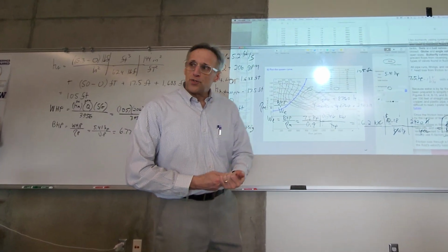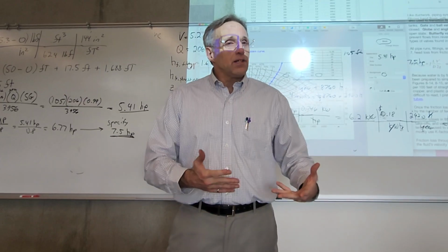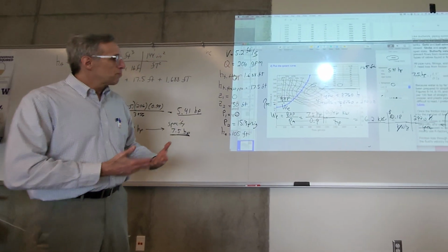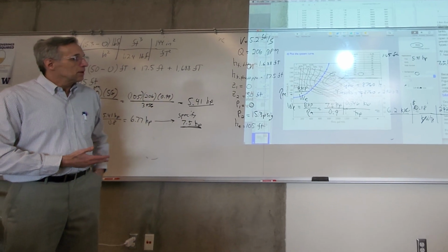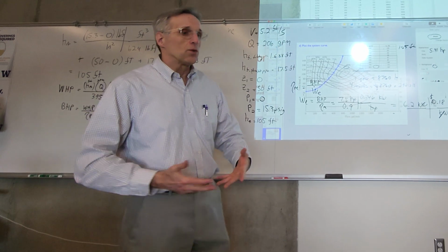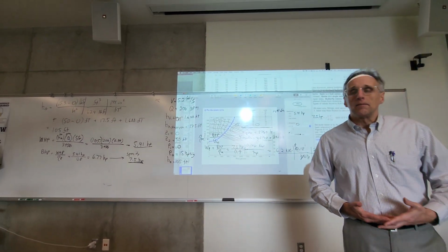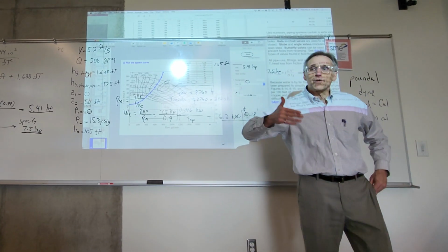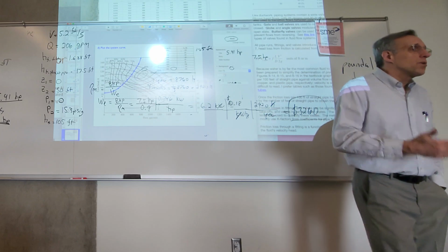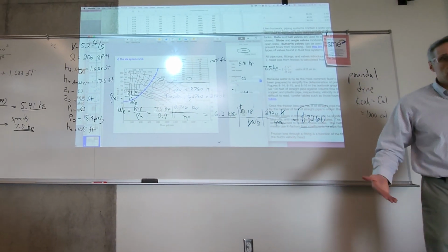Actually, I don't know if you're going to do energy recovery or not, but I was not planning to do energy recovery until I heard from our presenters. I can't remember who, but actually now building codes, especially in the city of Seattle, require that you do energy recovery in anything bigger than residential. You've got to have an energy recovery system. So energy recovery systems, I think that's going to be part of your design, just an expectation that you include that.